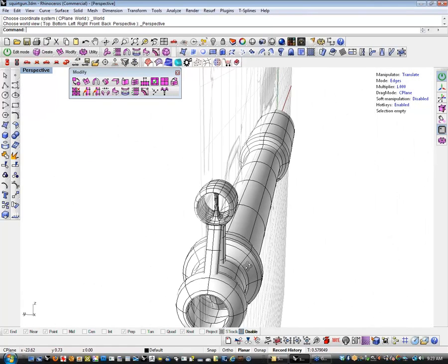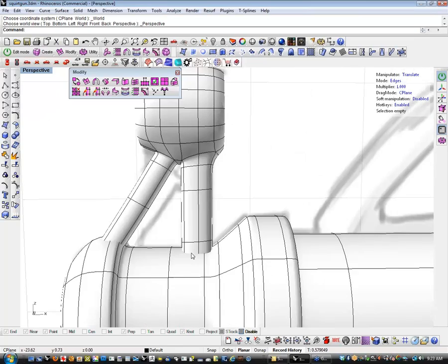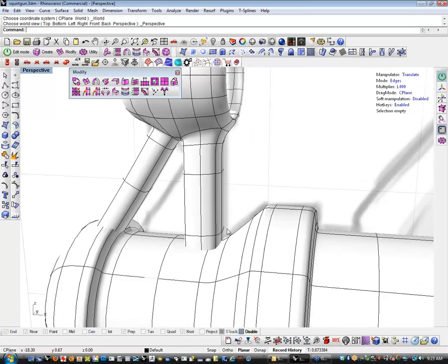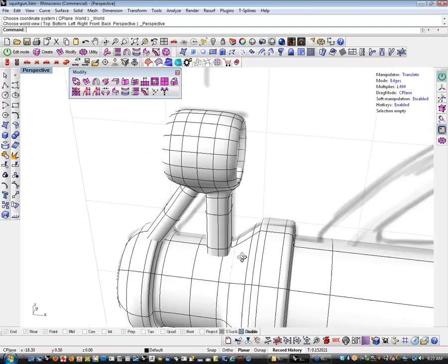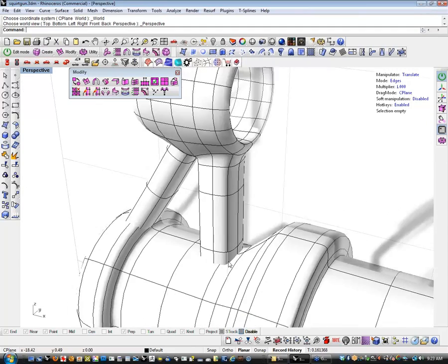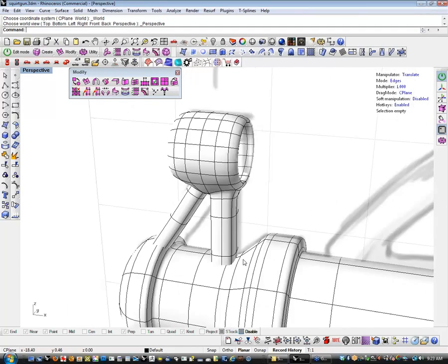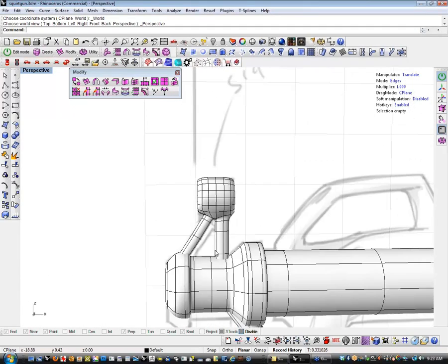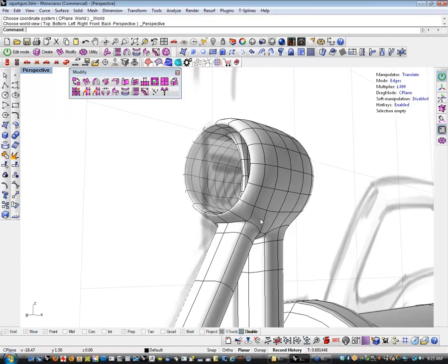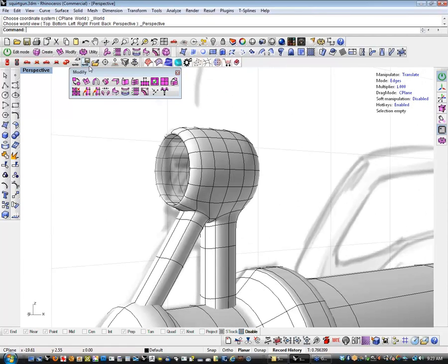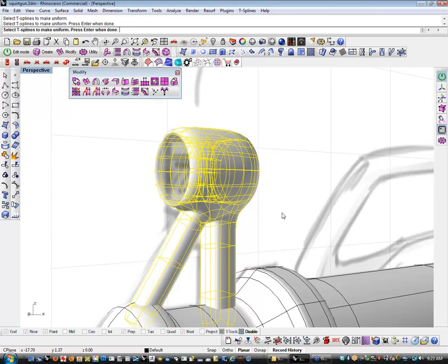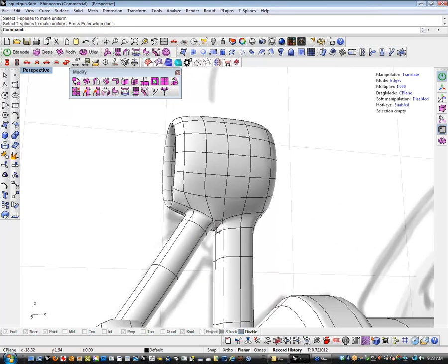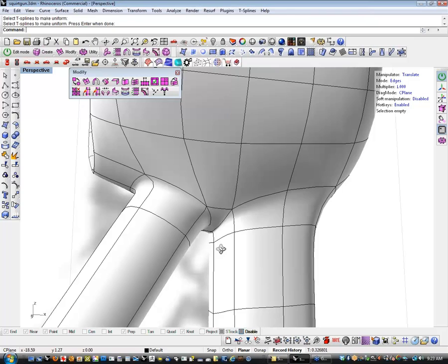So that's pretty good. And I've got plenty of intersecting surface down in here that I can go in and Boolean this together when I'm done. That should fill it together nicely and all that kind of stuff. So let me just run a make uniform on this guy since I added some extrusions to it, just to make sure everything is settled.